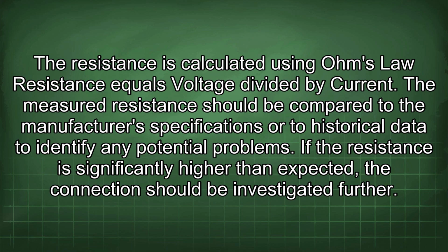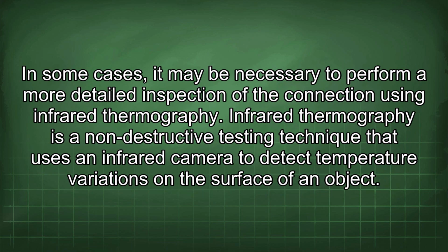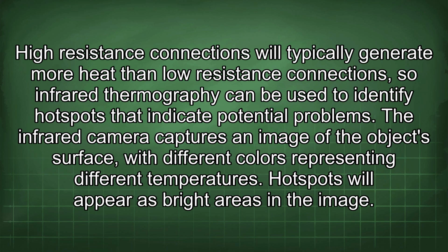The measured resistance should be compared to the manufacturer's specifications or to historical data to identify any potential problems. If the resistance is significantly higher than expected, the connection should be investigated further. In some cases, it may be necessary to perform a more detailed inspection of the connection using infrared thermography. Infrared thermography is a non-destructive testing technique that uses an infrared camera to detect temperature variations on the surface of an object. High-resistance connections will typically generate more heat than low-resistance connections, so infrared thermography can be used to identify hotspots that indicate potential problems.